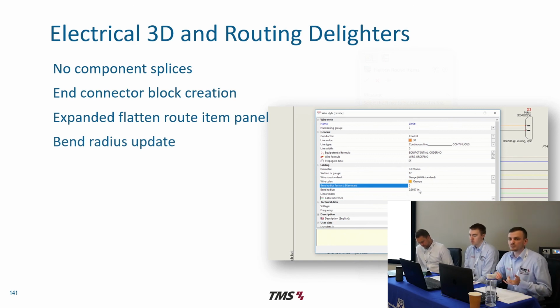But with this, we then have no control over our minimum bend radiuses for any of our cables or wires in there. So what we can now do within SOLIDWORKS Electrical is define this minimum bend radius or even a bend factor in there, depending on which one you enter. It'll calculate the other one for us. That way, when the mechanical engineer takes over, all this information is already within the project, so it's going to pick up those minimum bend radiuses that we want to follow. Again, just making it a little bit more accurate to what you'd have in real life.